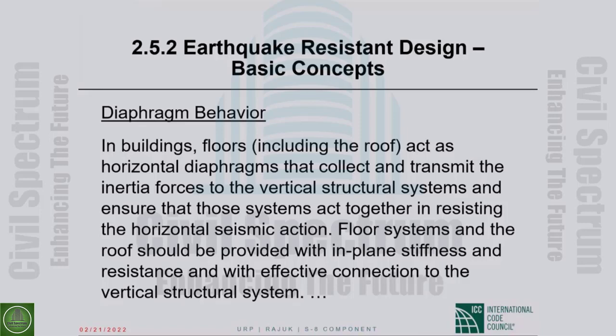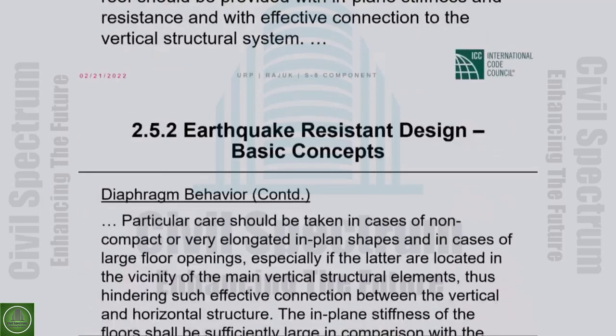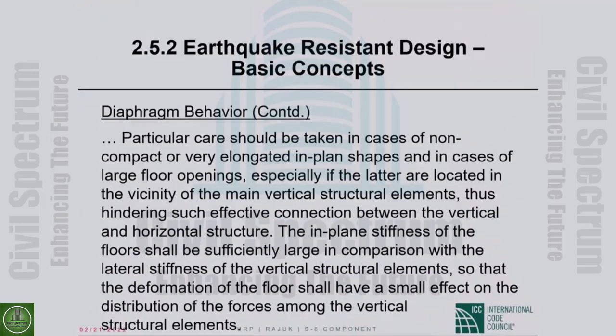Anyway, this is very basic. Floor systems and the roof should be provided with in-plane stiffness and resistance and with effective connection to the vertical structural system. Particular care should be taken in cases of non-compact. That means one side is very large compared to the other.